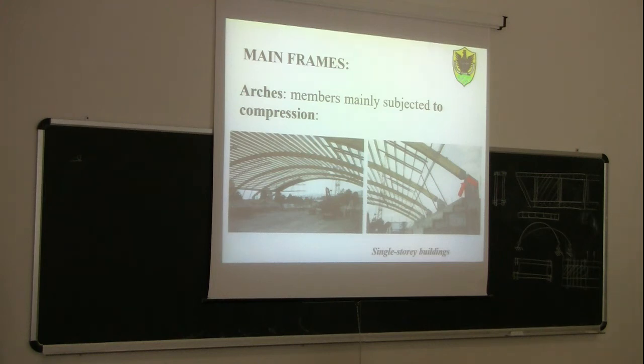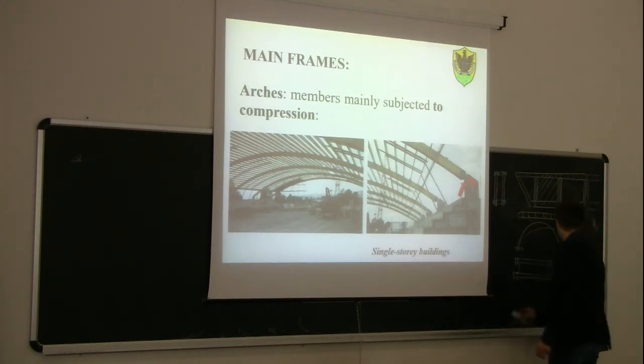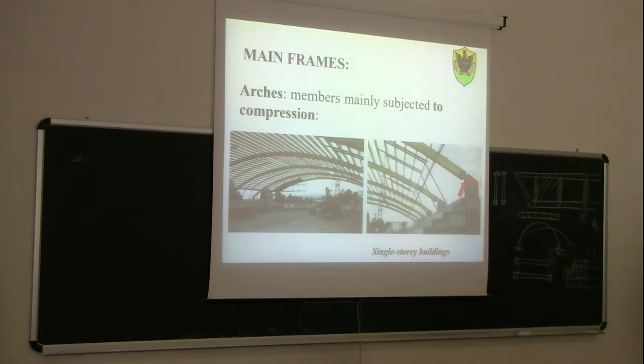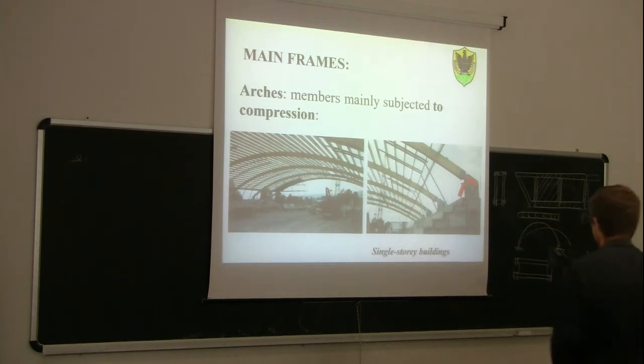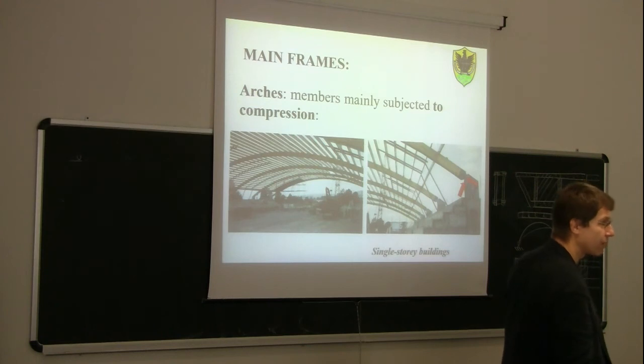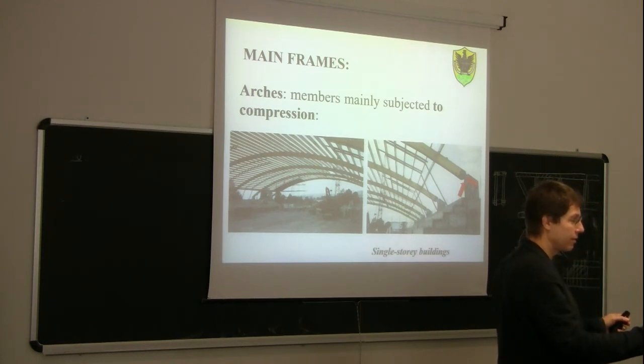Okay? Instead, if we prevent this displacement, so if we consider a pin, then you will find that this is a real arch. So then you will find that in this case, since we have a restraint reaction, the most important internal force would be compression. So remember that in an arch, it's very important that you prevent the displacement at the restraint of the arch itself.